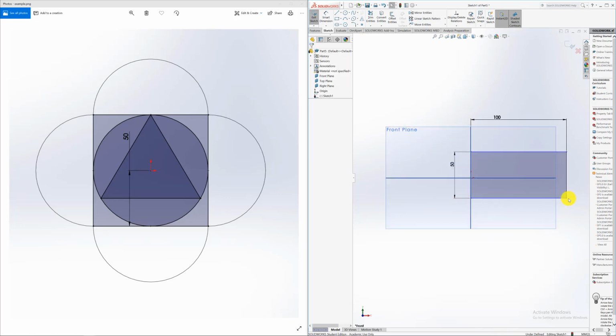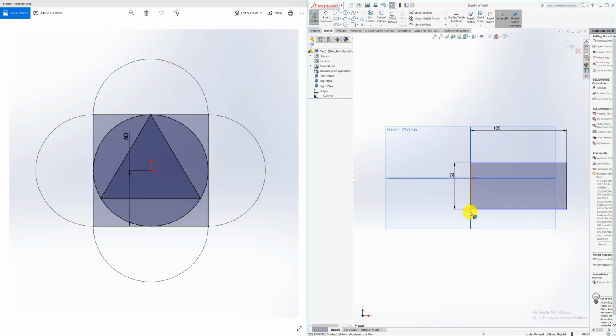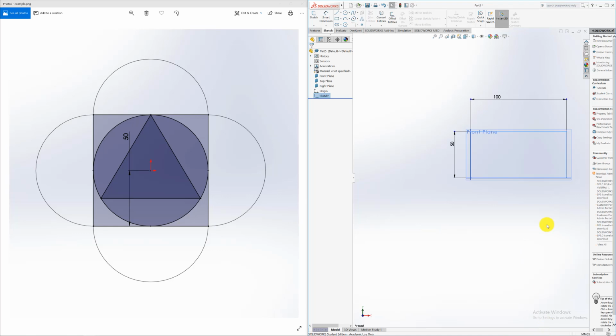But in this case, look like that. I'm going to do the same movement, it only moves up and down because it's snapped to the center line. So it takes that as a snapping point, a coincident point on this vertical line. So make sure of these things. You can always just go and delete these ones just to make it a bit movable again. Maybe you just want to snap it to there. So if you snap it to there, it automatically goes fully defined.